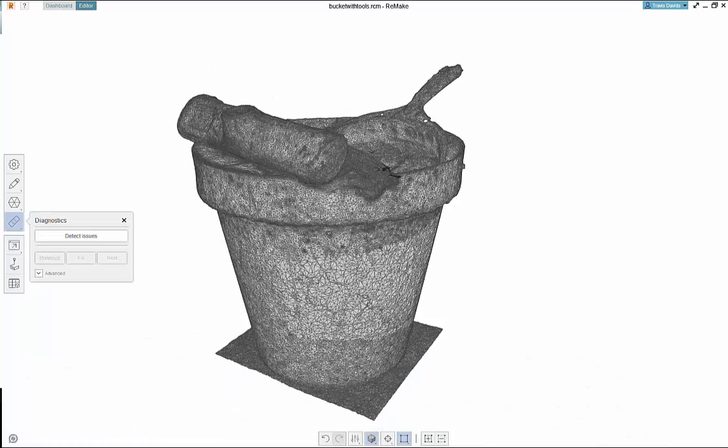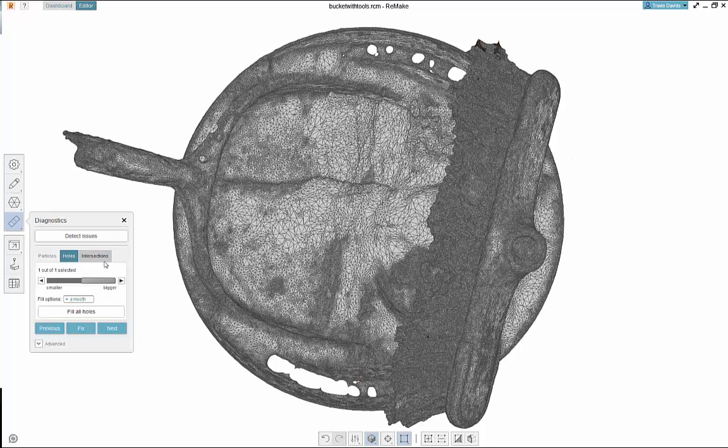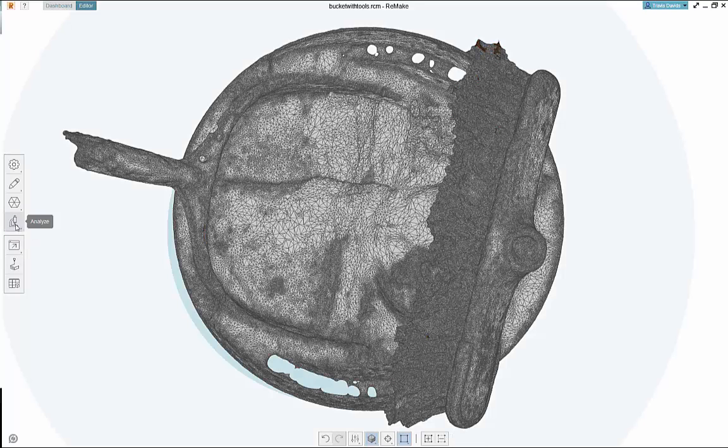So it's going to try its best to find any issues on your model. It starts looking for defects, and then it's going to bring up a dialog box that's going to say you have maybe 30 open holes or broken pieces on the mesh, and you can just automatically fix that for you. As you can see there, it's telling me I have one hole, I've got 24 intersections over here, and we can choose to remove all and let this, basically it's like an automated process that tries to fix errors for you, so that can actually come in handy.